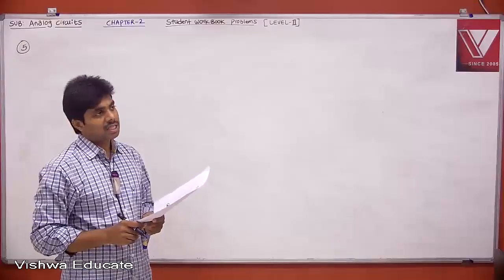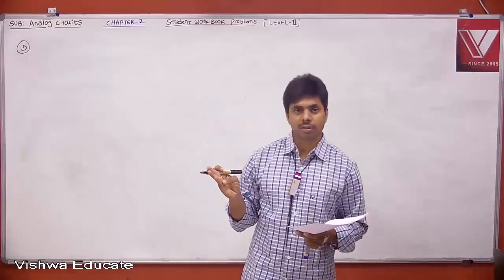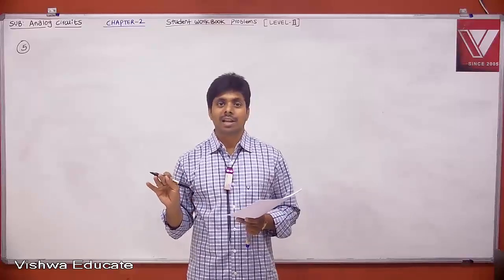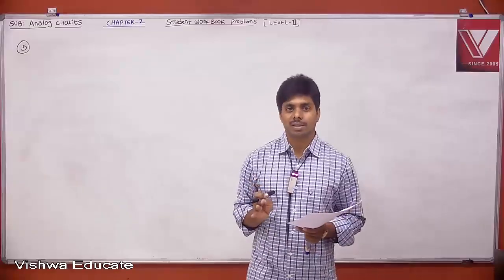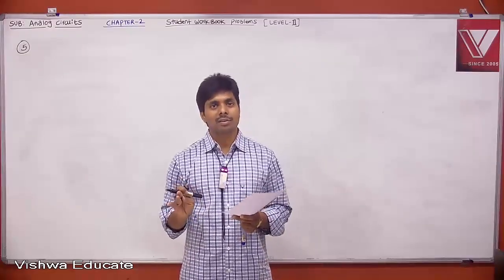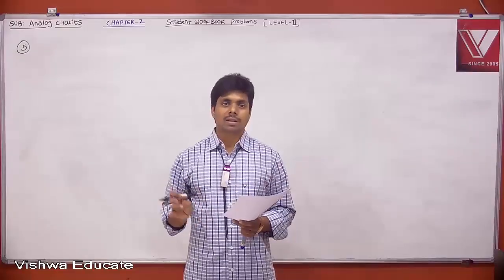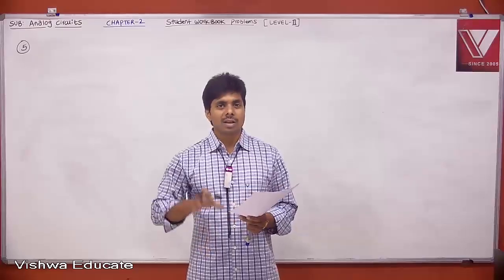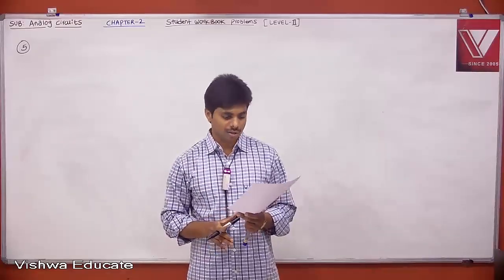Okay. Actually, how many bias circuits had we seen? 3 only: fixed bias circuit, collector to base bias circuit, and self bias circuit. I told that collector to base bias circuit and self bias circuit both have almost the same stability. But due to the final implementation including AC analysis plus DC analysis, the collector to base bias circuit needs what? Inductor. We don't want to use an inductor. That's why I told that we go for self bias circuit.